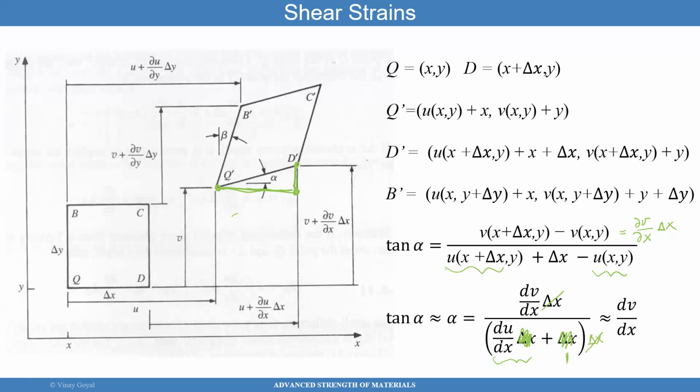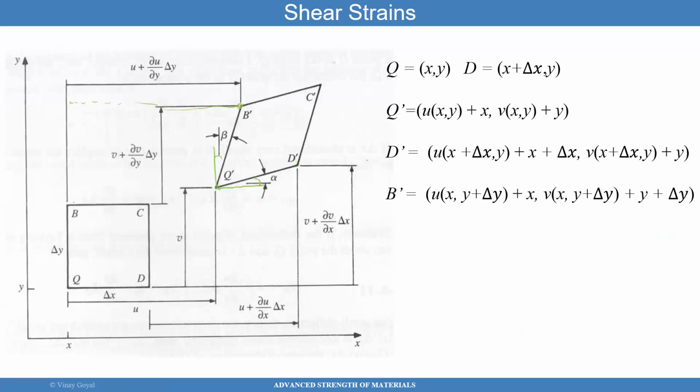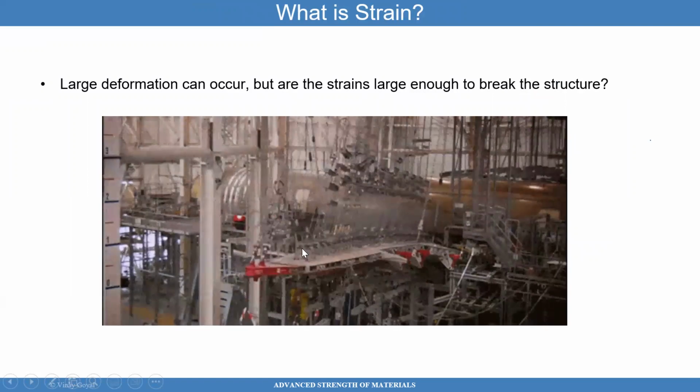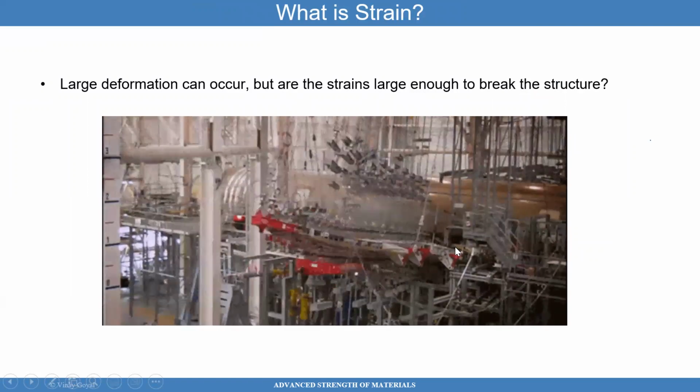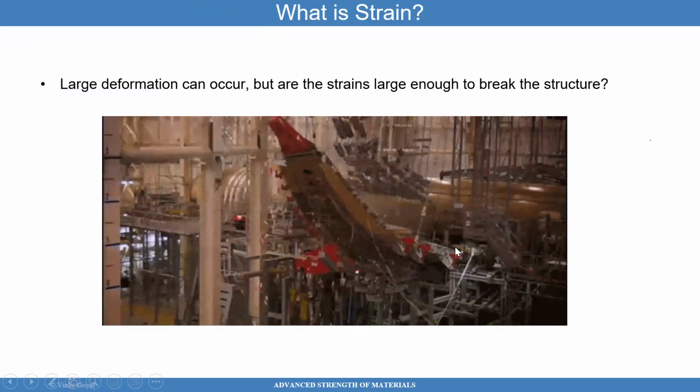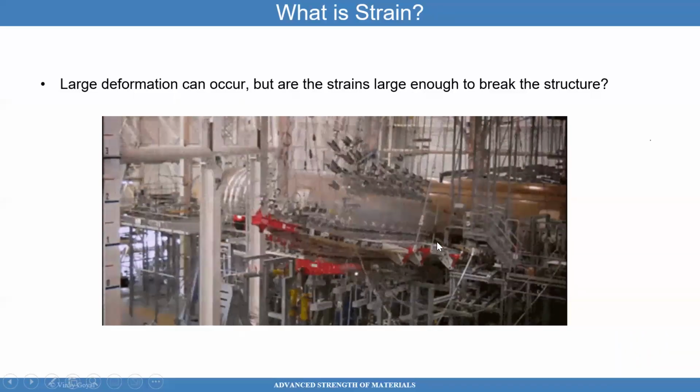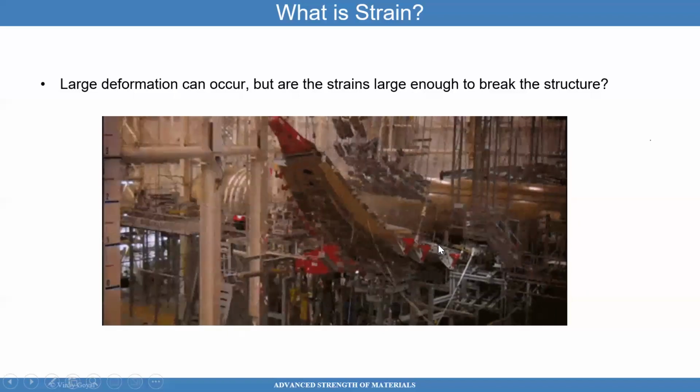And because du/dx is so small, here I'm exaggerating the deformation so you can see how things deform. But in real life, these are very small deformations. The strains, even in this aircraft wing that's deforming quite significantly at ultimate loads, where they apply a factor of safety of 1.5 for airplanes, shouldn't exceed more than 2%.